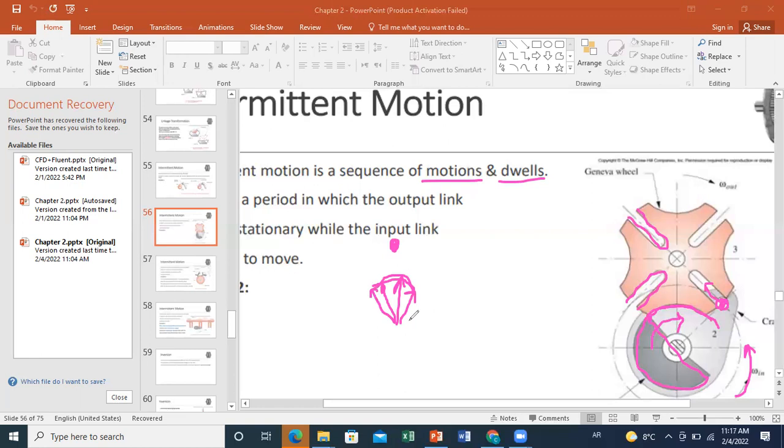Since forces are transmitted perpendicular to contact, when you want to find the resultant force transmitted, if you divide it into components, into normal and tangential components, you will see that, what do we mean by normal component? A normal component is directed towards the radius of rotation, and a tangential component is directed, if you want, in a direction perpendicular to the radius. When you do the summation, you will see that tangential components will cancel out, and you will only have a net normal component.